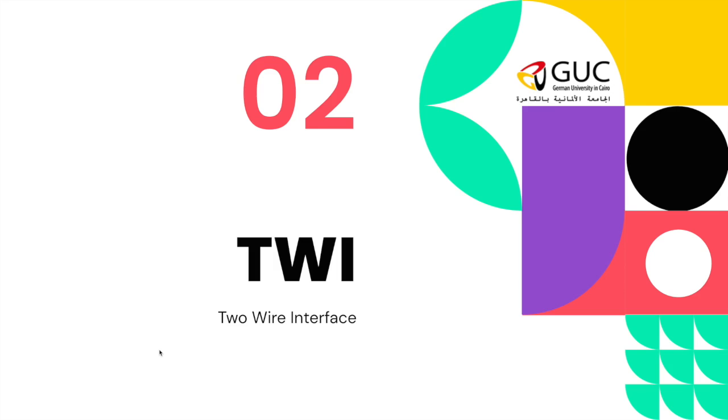Moving on to the second part of our tutorial, which is the two-wire interface, TWI, which is another name for the I2C. Atmega microcontrollers implement I2C, the same exact concept of having two wires, the SDA and the SCL. However, they call it a different name. They do not use the I2C name, they call it the two-wire interface, which makes sense because we have two wires, serial data and serial clock. So do not get confused. TWI is I2C, but it is a different naming used by the Atmega microcontrollers.